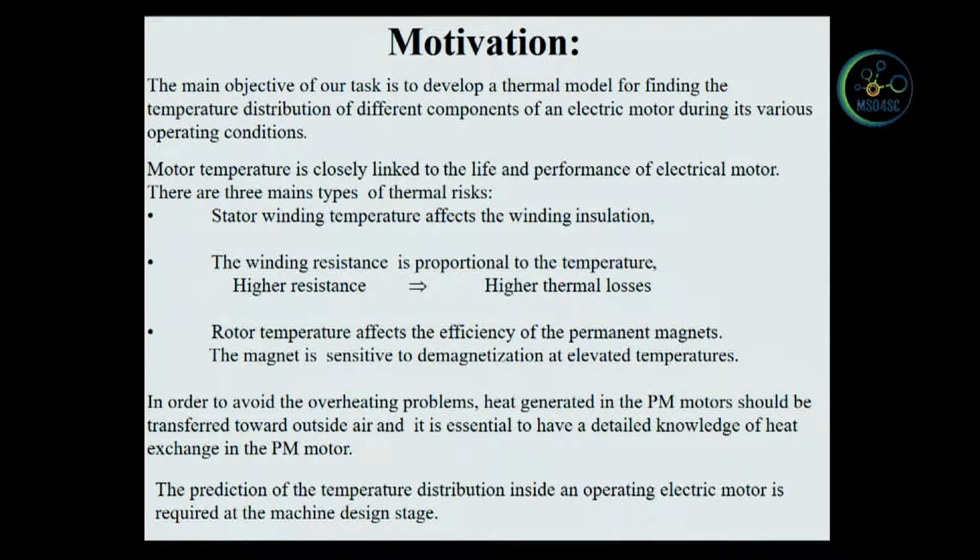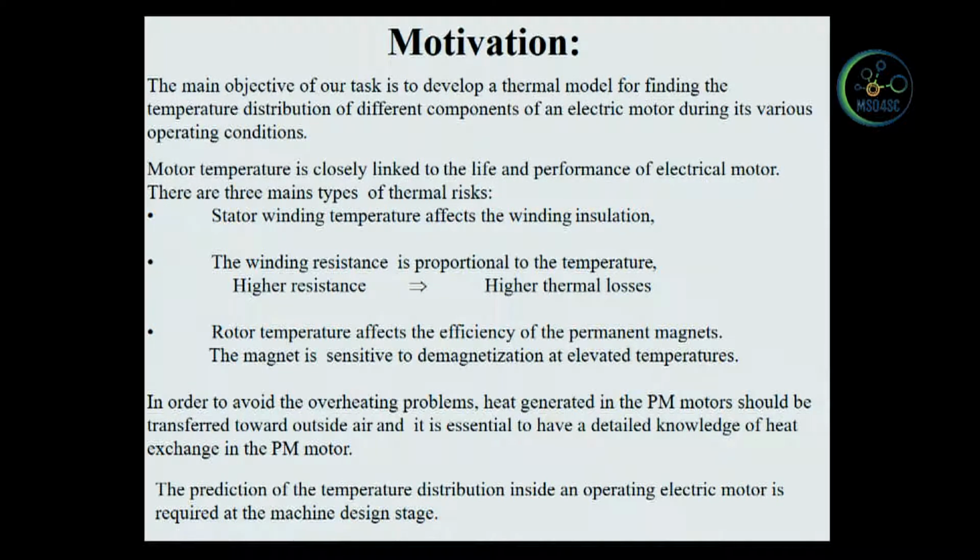In order to avoid the overheating problem, heat generated in the PM motors should be transferred toward the outside air, and it's essential to have a detailed knowledge of the heat exchange in the PM motor. The prediction of the temperature distribution in an operating electric motor is required at the machine design stage.